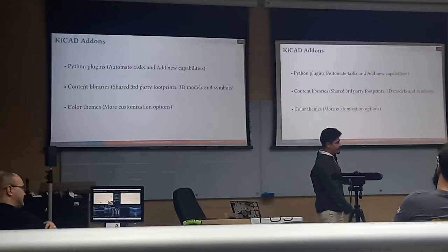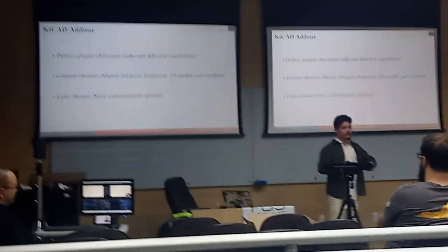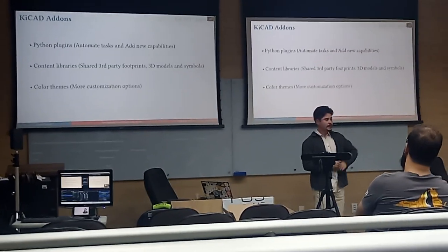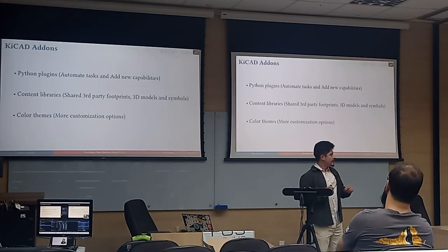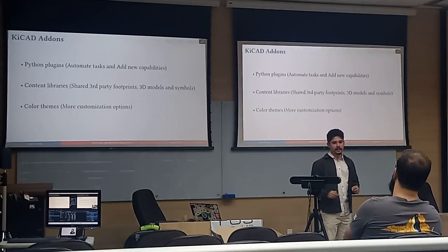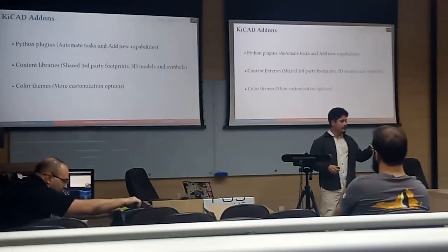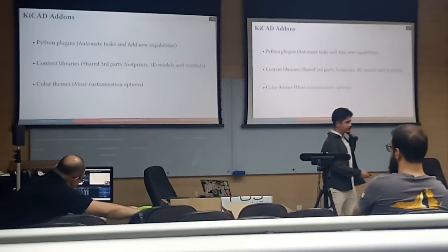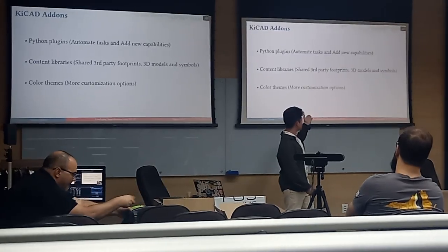Because they have nice KiCad add-ons. There are plugins for KiCad. Because KiCad is scriptable, you can make scripts, and you can share the scripts with the KiCad add-ons. So you can have, for example, new capabilities. For example, you can make KiCad do parasitic extraction. That is not so common, I think, for PCB designs, but for semiconductor designs it is very common. But you can implement this. Actually, KiCad has one of these. You can make automation tools, as I will show here.